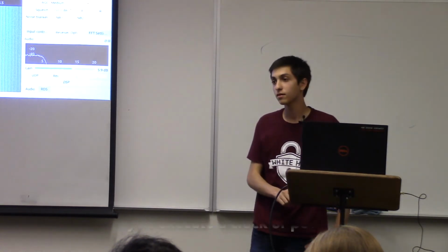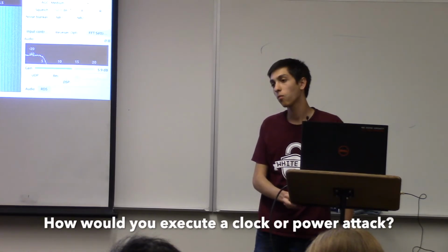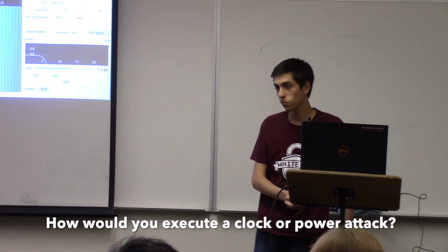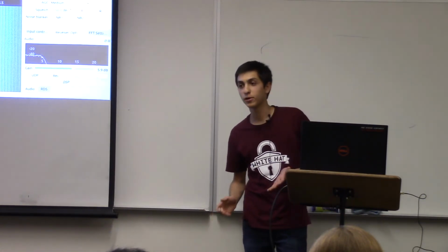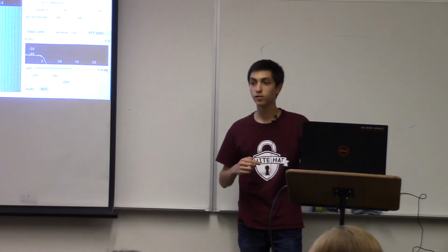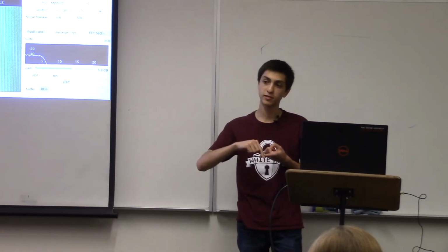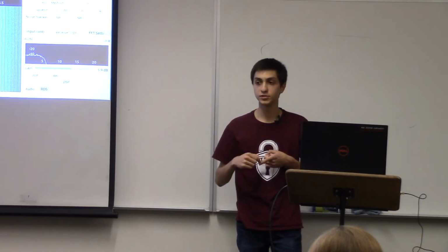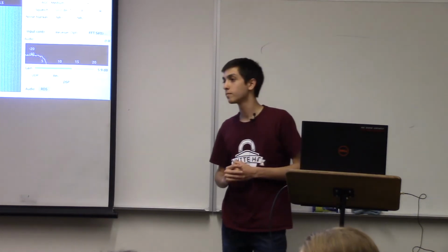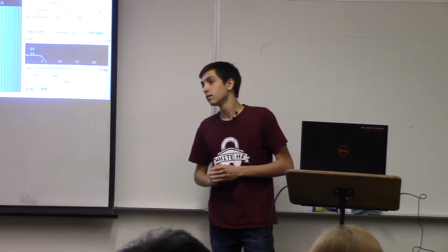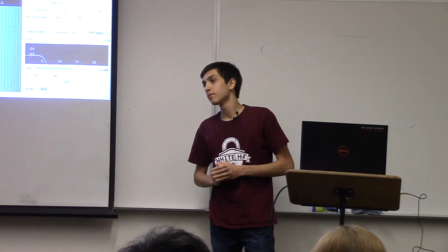So earlier on you were talking about the clock attack and the power attack. How would you actually go about executing those? You take a piece of hardware, open it up, figure out where the clock's coming from, tap into that signal, and then introduce those errors. Okay, cool. On that note, how do you time that kind of injection of the clock?